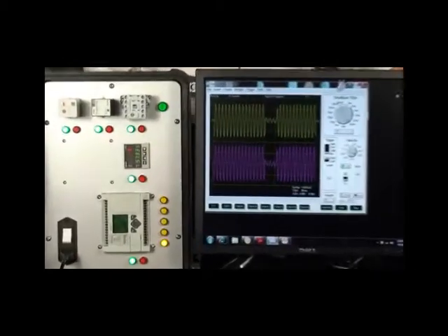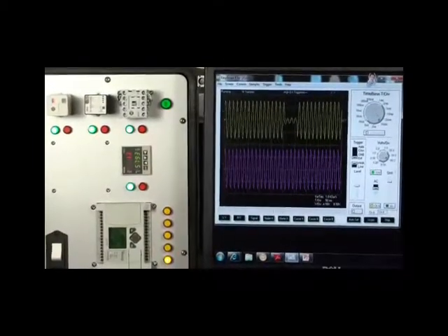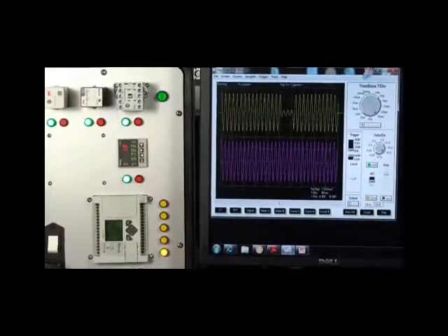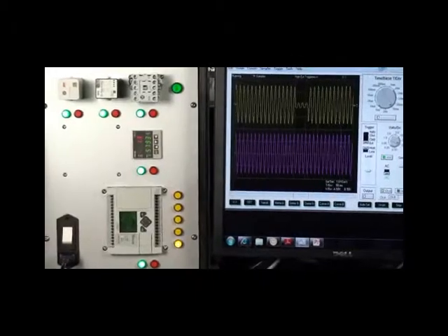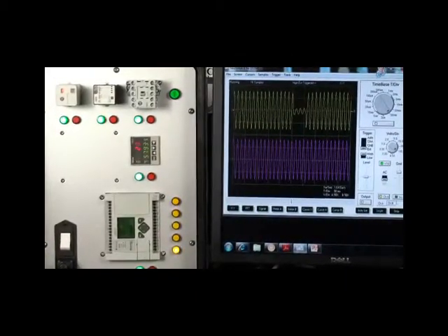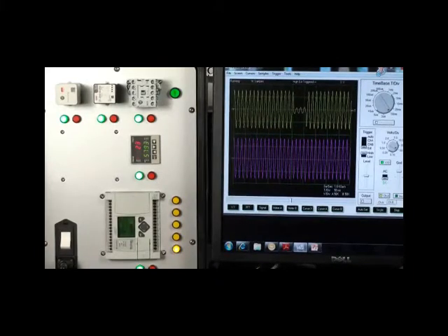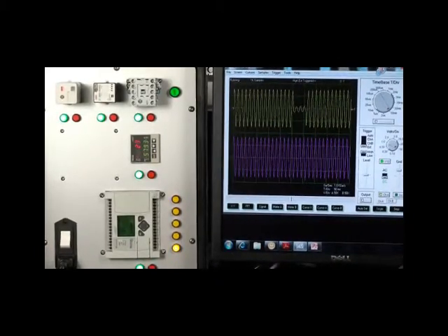And if you look at the monitor, you'll actually see that waveform reappear on the top of the screen, showing the sag generator created that sag, but if you notice on the bottom of the screen, the load never saw it. The DySC came on, turned on, and recreated the sine wave during that period of time.